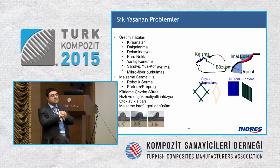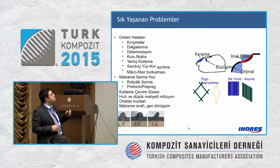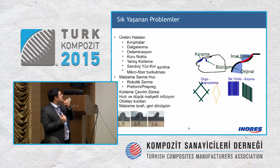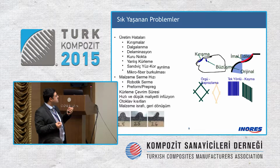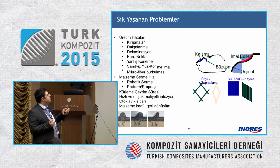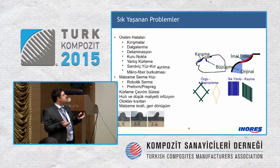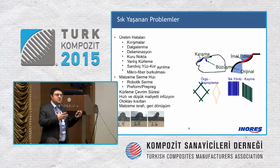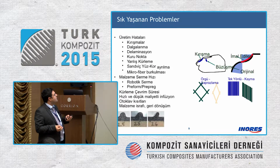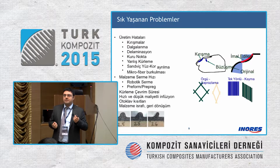The fabric is flexible and it can crease when it's not handled properly. Waving and delamination might occur, and if the fiber is not wetted totally, there might be some dry points. Wrong curing, sandwich face-core separation, and microfiber creasing might happen. Of course, in order to have profitable and high quality production, we need to lay it as fast as possible, and we have to use products which have been prepared before.